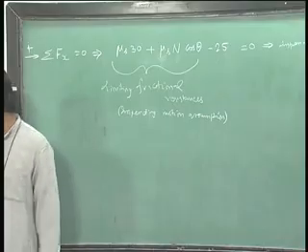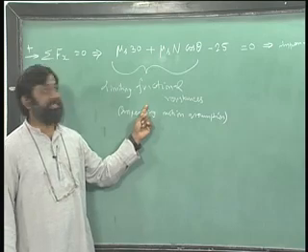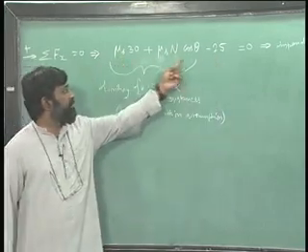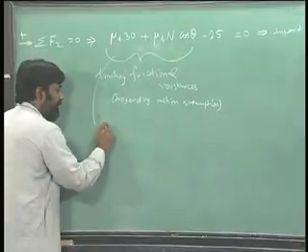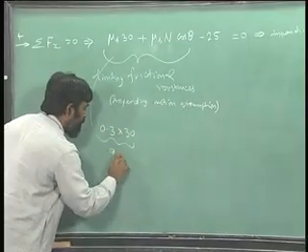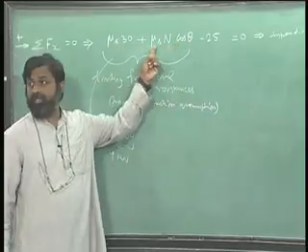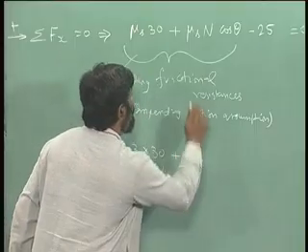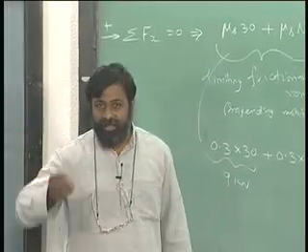So, this is again impending, this is only due to the frictional resistances, and this is what is applied. Let us just estimate what this could be. I am going to do a rough estimate here. Mu s is 0.3, so this is 0.3 times 30, which happens to be 9 kilonewtons, and I have a cos theta times mu s, that is plus 0.3 times cos 30.